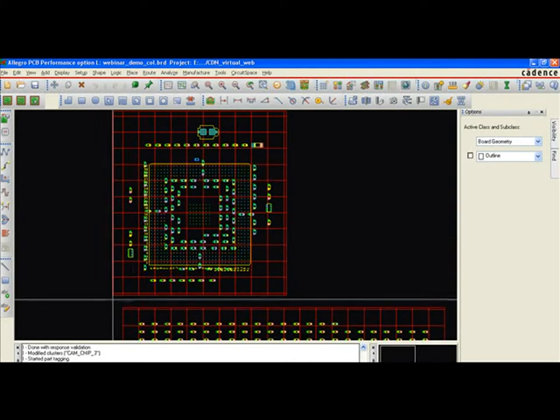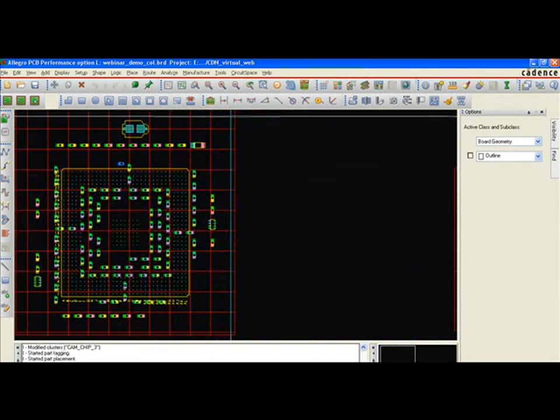Using the autoplace command, you will see that CircuitSpace has positioned all the discrete parts around the IC. This command uses the CircuitSpace algorithms, which take into account connectivity, as well as voltage requirements and fan-out requirements to provide a valid placement. Of course, the designer is free to massage and tweak the placement to their liking at all stages of this process.